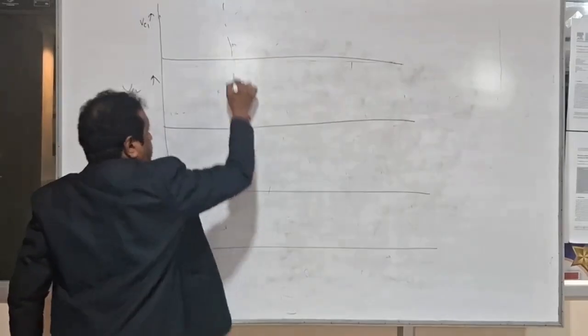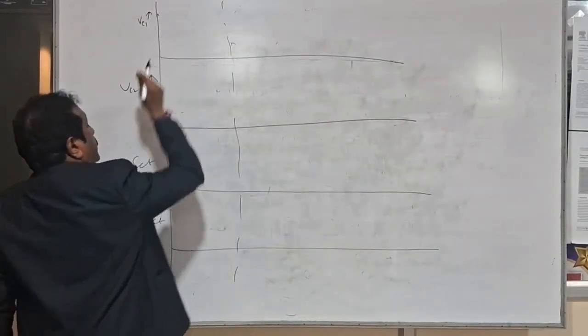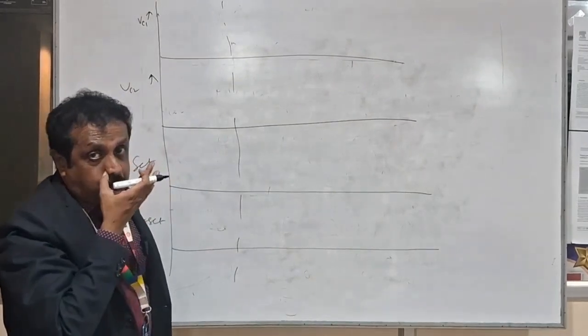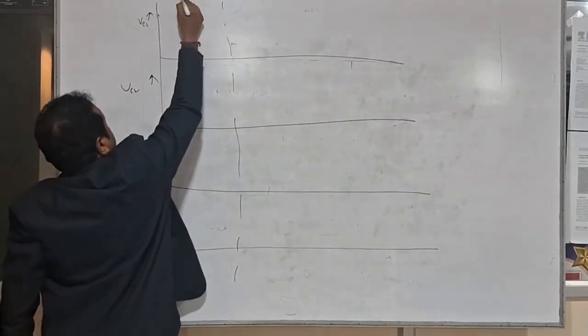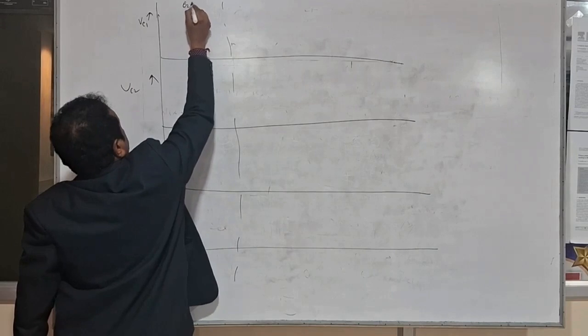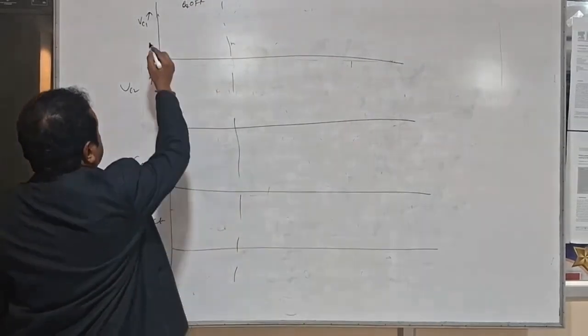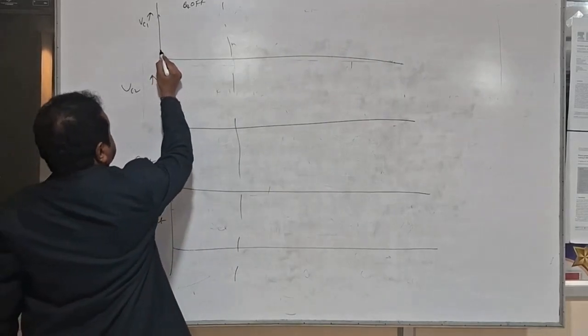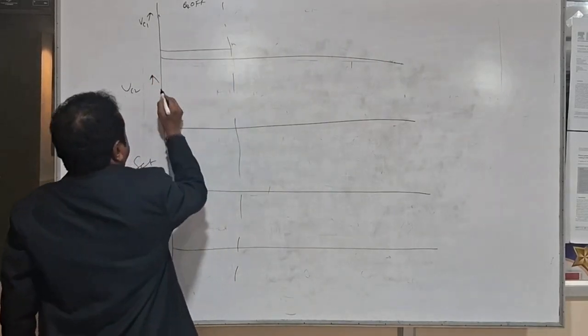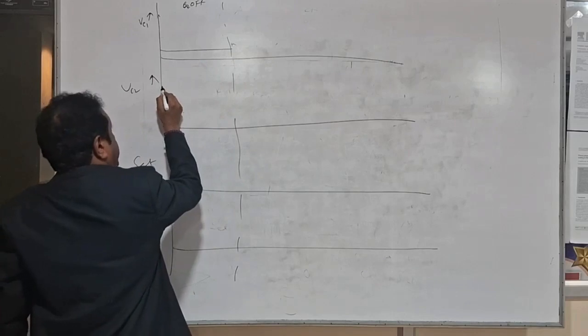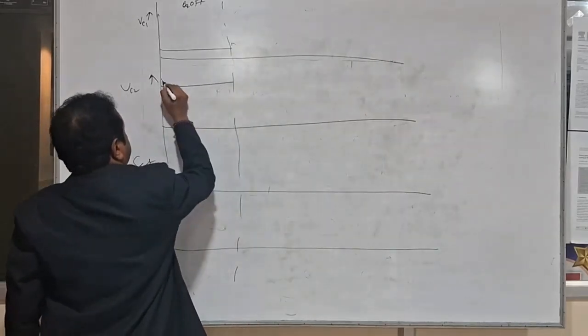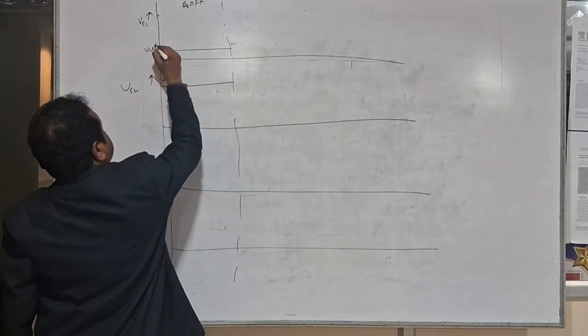The initial state of the bistable is due to some imbalance. We have assumed Q1 is on and Q2 is off. That is the assumption only. So when Q1 is on, the corresponding collector voltage is VC saturation. But for Q2, which is off, the output VC is high.